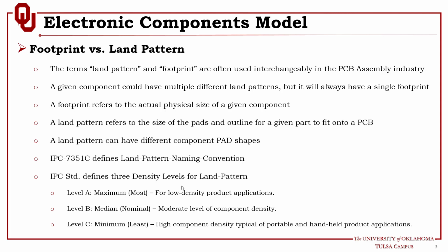The footprint is the physical exact size of the electronic component on the PCB layout, and the land pattern should always be slightly larger than the footprint of any component. And you can always find land pattern recommendations in the manufacturer datasheet as well as in the IPC standard. And these land patterns, whenever they are defined in the datasheet, follow the IPC standard for land pattern. And we'll talk about this standard as well. So, footprint versus land pattern.